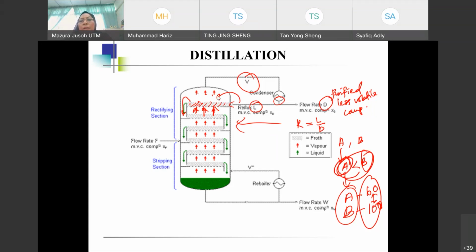So if you have the reflux coming in, it is not mainly to maintain the temperature profile, because what maintains the temperature profile is the reboiler. Okay, so it's good that you are thinking towards the temperature as well, but I will explain to you how it works in a while.